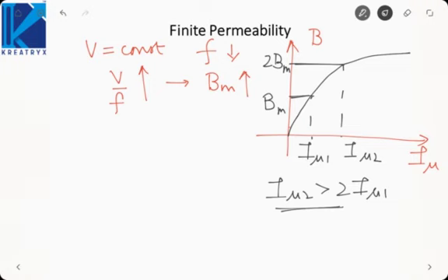It will damage the power factor of the machine. That is why we do not desire the magnetizing current. That is why I was assuming that an ideal transformer has infinite permeability. Infinite permeability signifies zero magnetizing current. Magnetizing current always worsens the power factor of a machine. So here the magnetizing current will increase immensely and the power factor will be worse.